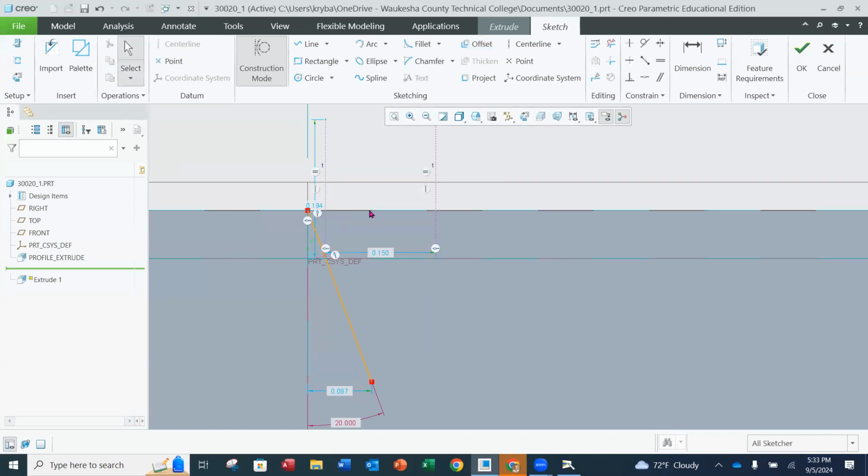We're going to say okay, and change that value, double click on that value, 0.06545, and then enter. It's going to be better. You can see it already. This line that we just created is our mirror line. This is the correct placement of the mirror line. Okay, so I'm going to click off of that and take the construction mode off. We're going to select our angled line and mirror it over the construction line we just created. There we go. So that is in place.